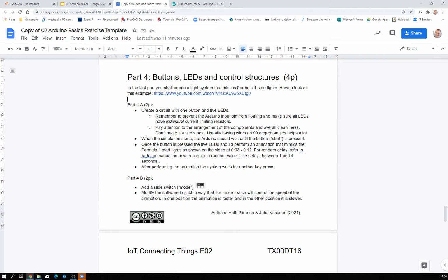There are a couple of questions here. Just use pull up. Yes. Debounce required? Okay, debounce not in this simulator environment. Those are more or less perfect switches. You know it's not true, but it's a simulator.